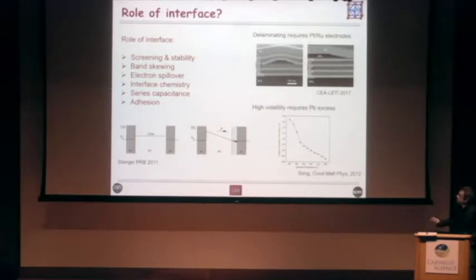And then other questions such as adhesion. Adhesion is illustrated here. A favorite electrode on CMOS-compatible capacitors could be platinum. But when you use platinum, in fact, that delaminates after a certain number of cycles. And so the solution is platinum with a thin ruthenium layer between the platinum and the PZT. And there's no delamination, and that's something we're working on quite recently.